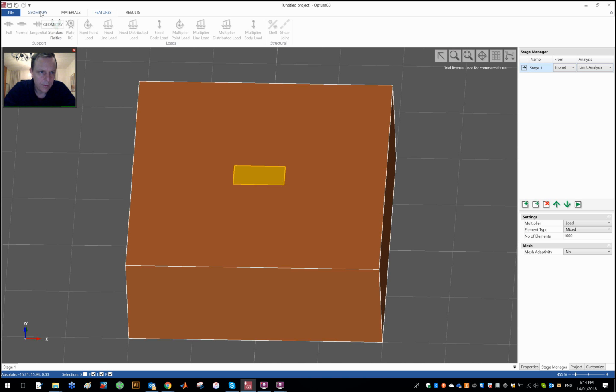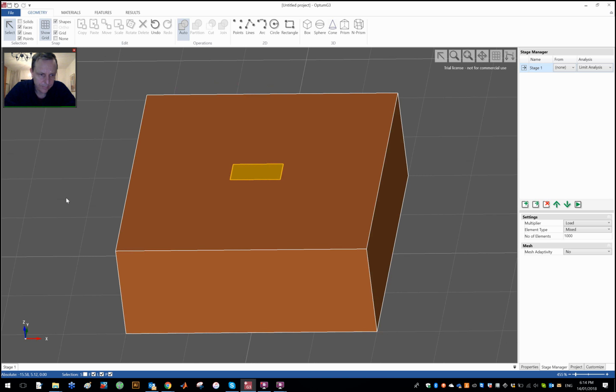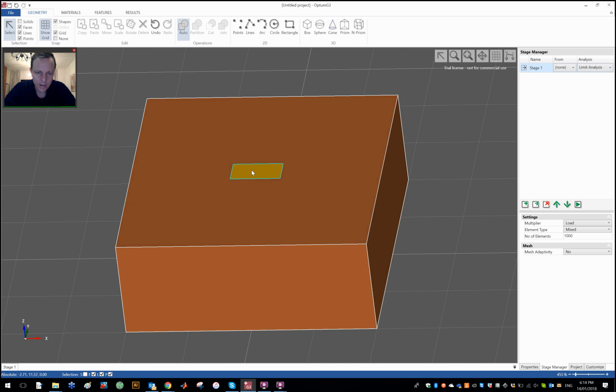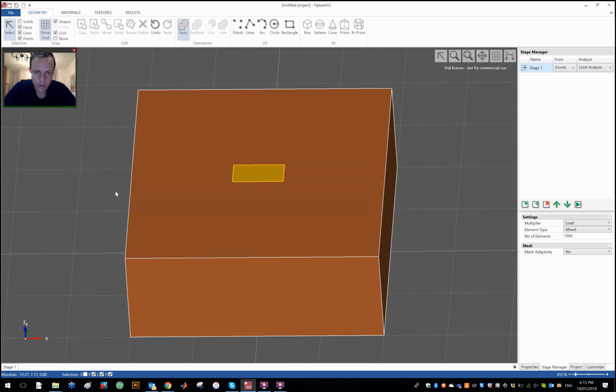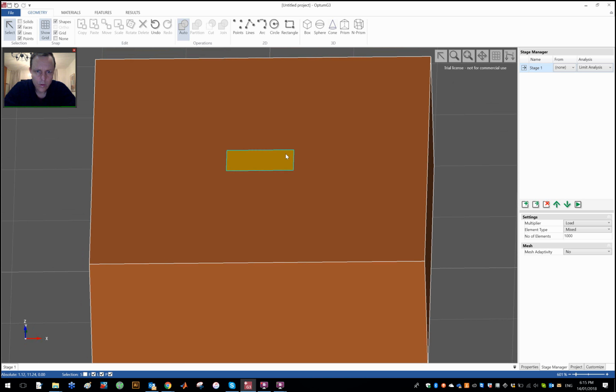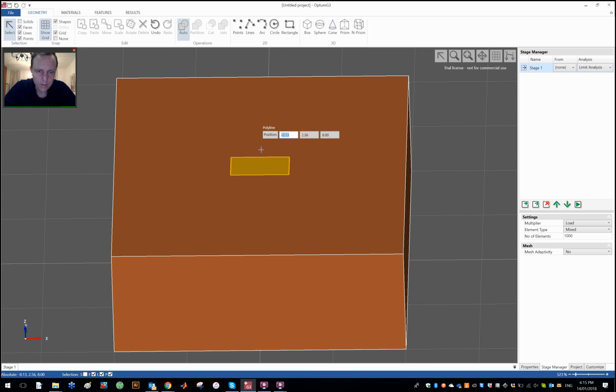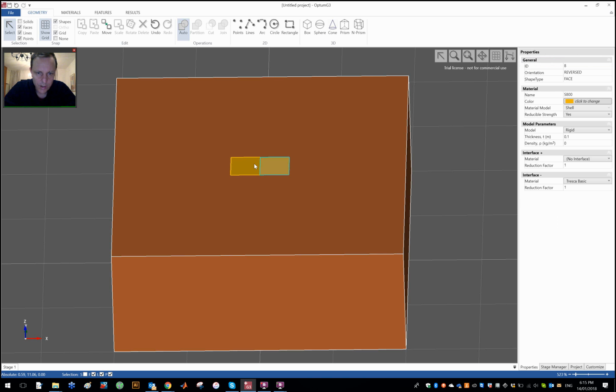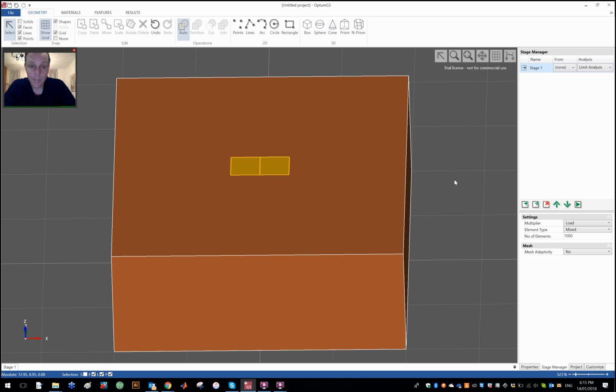And I'm going to subdivide that. So I want to apply moment about the y-axis basically, so have the moment in the most optimal way in relation to the dimensions of the foundation. So I'm going to subdivide the foundation before I do anything else with a line from 0, 1 down to 0, minus 1. So I now have 2 parts of the foundation.